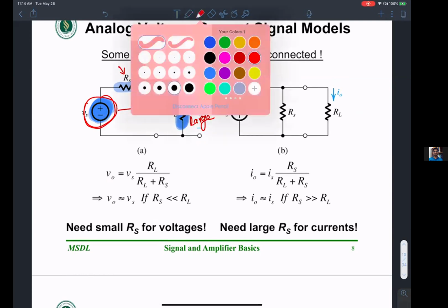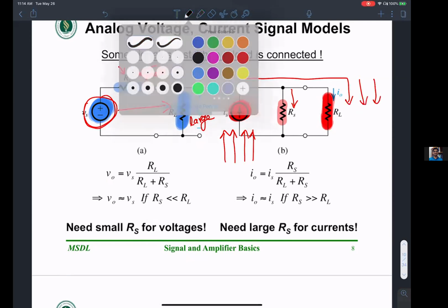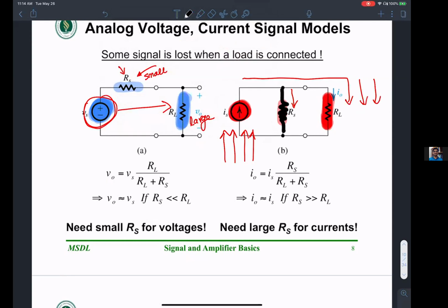On the other hand, let's think about the current here. My goal is that the current that I apply as the input signal, most of it should go through this resistance. Very little should go through this resistance. So think of it this way. There's a lot of cars coming in this branch. And you as the traffic controller, you want to make sure that a lot of cars flow through this branch here and very few cars go through this branch. How would you go about doing that? Well, what you do is you make sure that there's a lot of hindrances, stop signs in this path. There's a lot of resistance. If you keep a really, really large resistance in RS and a small resistance, very few signals and stoplights in this guy, then most of the traffic is going to go in this. Very little traffic is going to go down this parallel path.